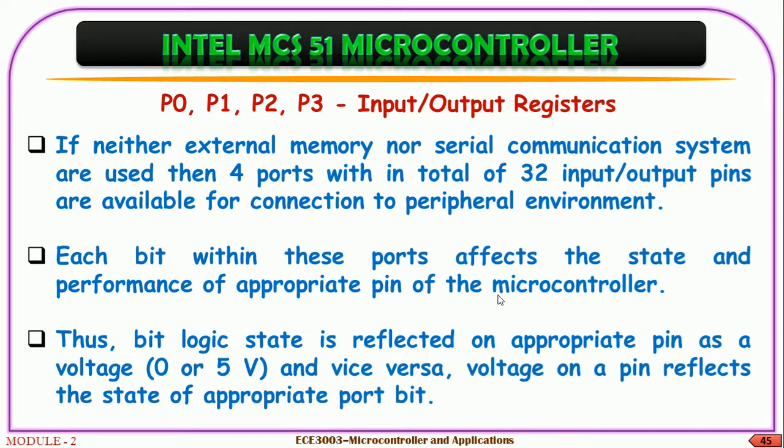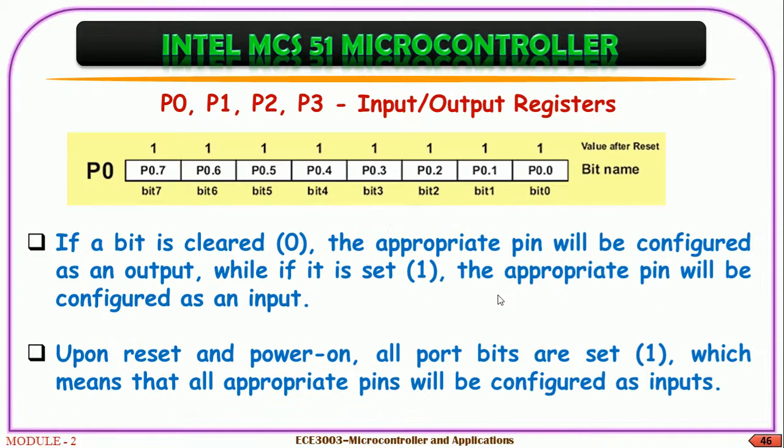Then P0, P1, P2, P3, the input and output registers. Each one is an 8-bit port, which is configured as input or output. If the port is set, then it acts as an input port. If the port is cleared, then the particular port acts as an output port.